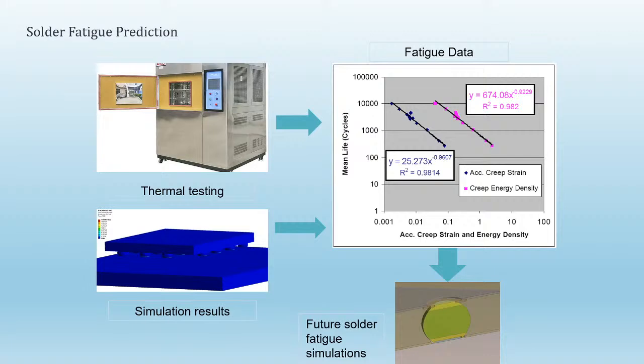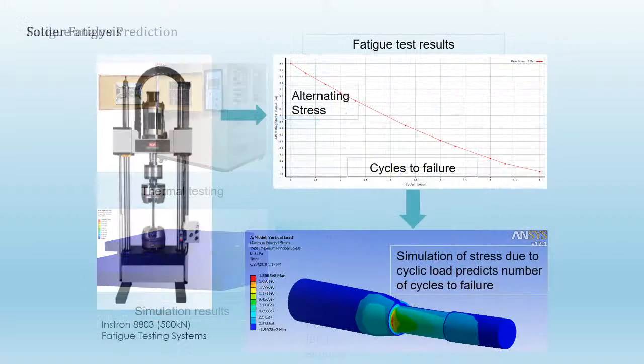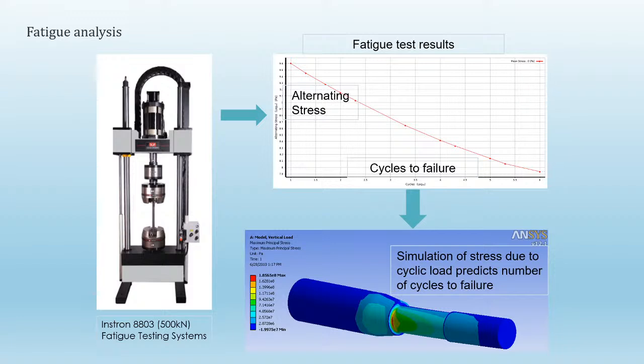I think the thing that I wanted to highlight with this fatigue analysis discussion is that whenever you're talking about durability, you're always looking at how your simulation results correlate to some sort of experimental value, right? In the fatigue analysis, we know from experiment that a particular stress will cause failure or crack to grow